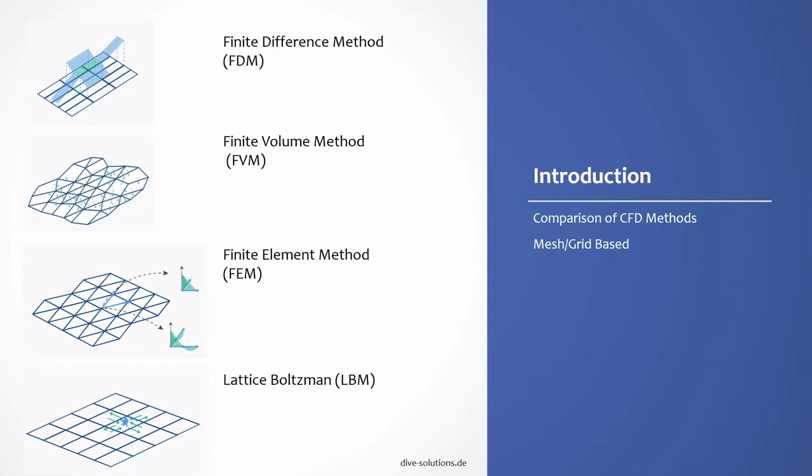Simple geometries are solved easily with FDM, where FVM is mainly used for fluid flow problems, and FEM has always been useful in solving problems with complex geometries. Grid-based numerical methods discretize or divide a continuum into small subdomains by use of a mesh. The individual grid points are connected by this mesh.